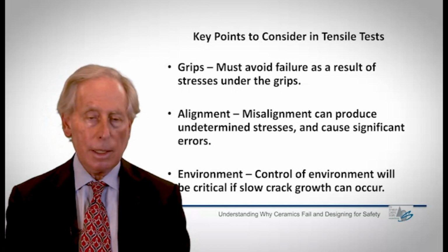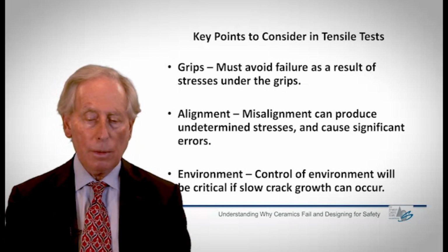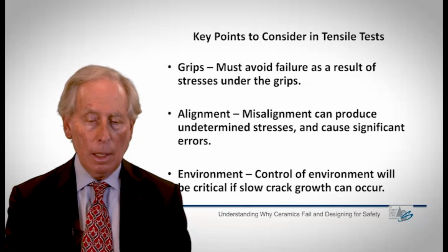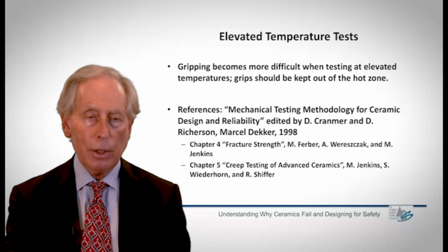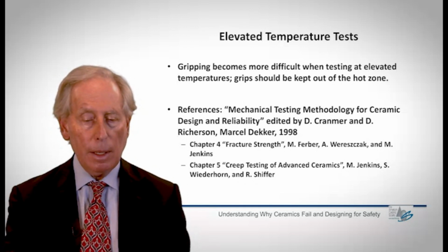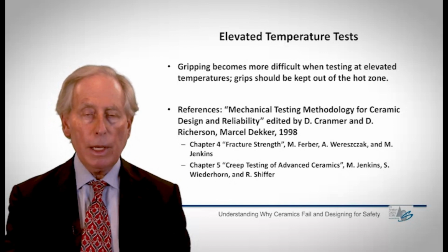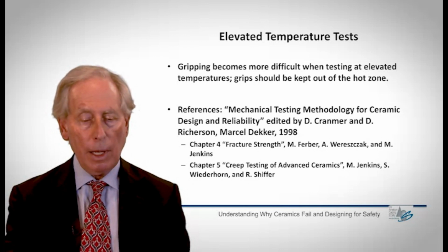So for tensile tests in the environment, if you're doing this at high temperature, you've got to do the tests themselves at high temperature. As I say, for elevated temperature tests, I'm not going to talk about the failure mechanisms at high temperature. They become quite different than what we see at ambient temperatures, but the gripping becomes more difficult when you're testing at high temperatures, and you've got to be careful to keep the grips out of the hot zone.